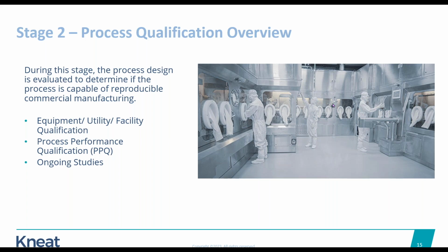So for this, you will have some documents that you have to complete. You'll have a PPQ protocol where all of your tests and samples will be recorded, that pre-planned protocol. You will also have a PPQ readiness checklist that will assess if there's any outstanding change controls or deviations that could impact the PPQ batches. If there is, a risk assessment would also take place there, and it will assess that all your documents are effective, things like that. It's a pretty long checklist.